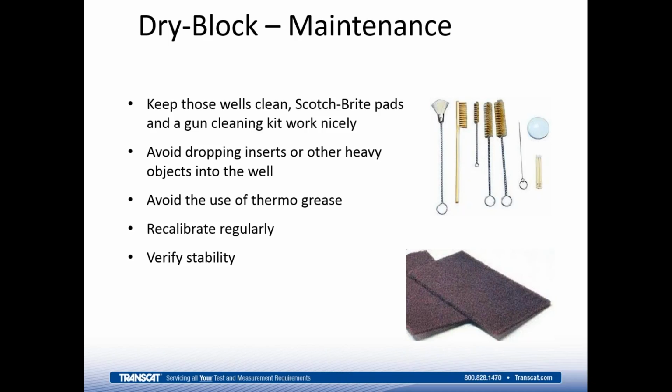The other thing to remind you of is that the dry block's supposed to be dry. If you stick thermal grease in there, good luck getting it cleaned up. It's going to be a problem for you for a long time. So I would avoid using the thermal grease.